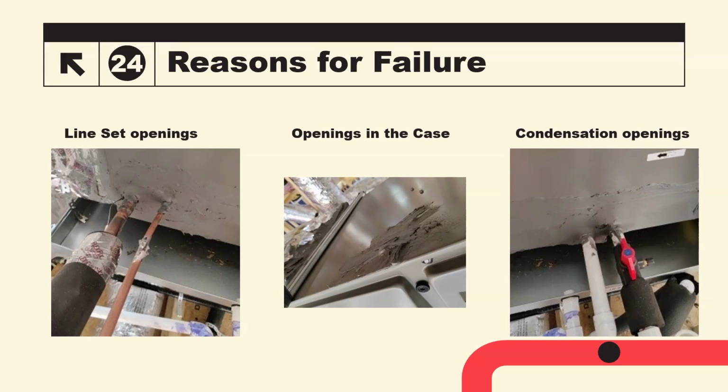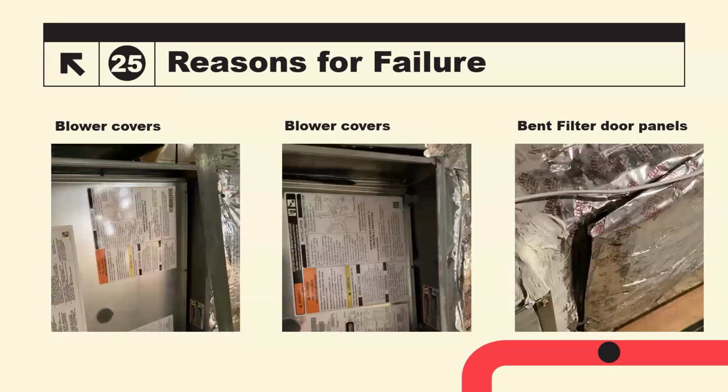So this is a great attempt at getting this to pass the first time. We always like to see this, because that just means the HVAC installer is going one step over what's kind of required of him to try to get it as tight as he can. And what you're helping it do is overcome some of the duct leakage that's going to happen anyway, because nothing's perfect. So you're just giving it a much better chance of passing.